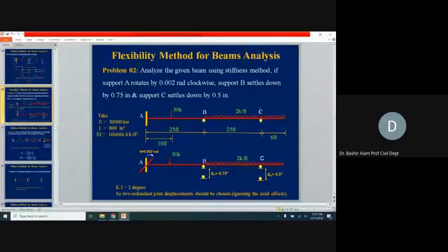So at joint C, if we take its equivalent effect, we can disregard this overhang portion. We can take its actions directly here. So this will become our 2-span problem, having roller support and roller support, and this overhang portion we will disregard because we will be taking its equivalent effect at joint C. So now it's a very comprehensive problem, having the rotation scenario, the deflections and settlements, and the overhang portion also.